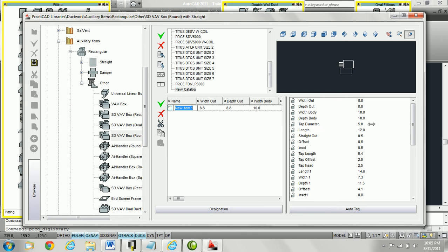If I wanted my offset parameters to be out to 1/8 of an inch, I will be unable to type all 3 decimal places necessary. So if I were to type in 2.875 and hit enter, you will notice that it is going to round these numbers up.